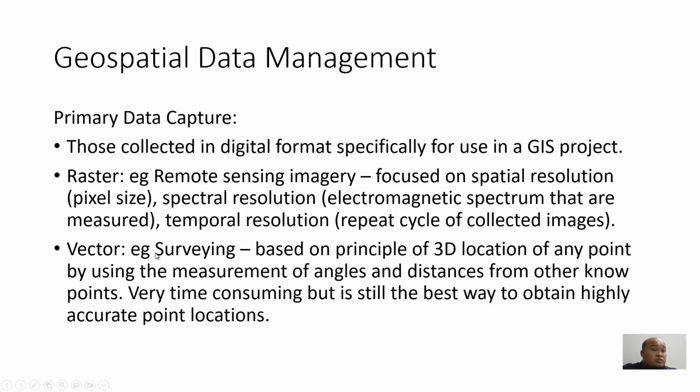Next is vector. Vector is more on surveying. Okay, surveying, there are many. There is total station surveying, GNSS surveying, LiDAR surveying, laser, 3D laser scanner. There are many. But all of them are based on the principle of finding the 3D location of any point by using the measurement of angles and distances from other known points.